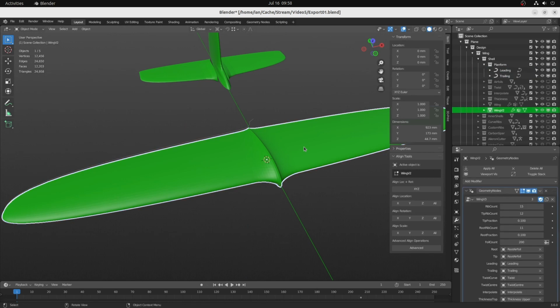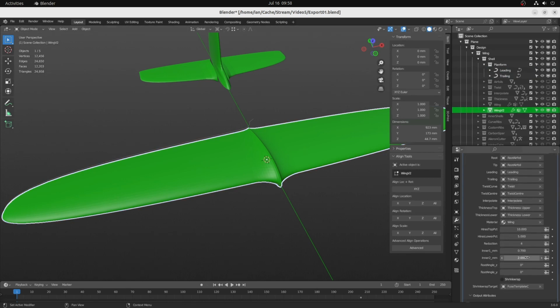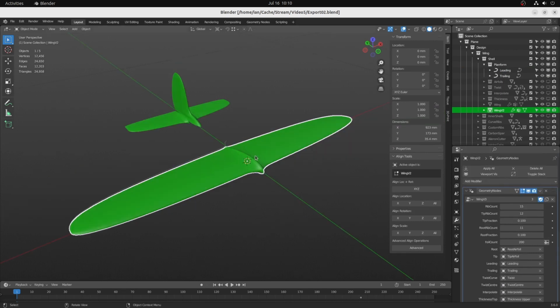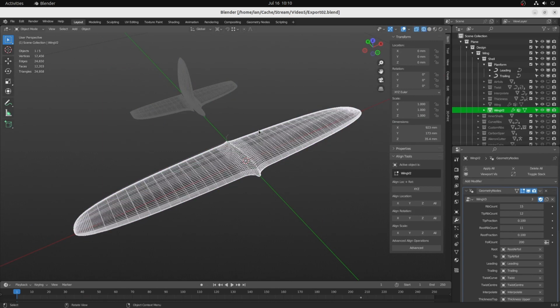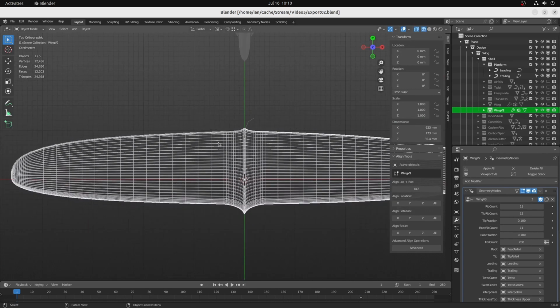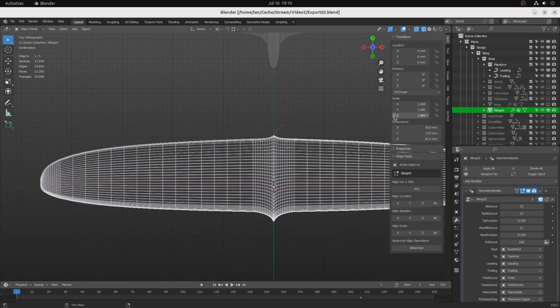The export add-on doesn't pay any attention to the wing joining features of the wing v2 object, like the shrink wrap and the X and Y angles, so I'll just turn these off to make it clearer what's going to be exported. Also, xFlr5 probably doesn't need as much geometry information as the 3D printer does. If you do export detailed geometry, it'll spend more time doing its calculations.